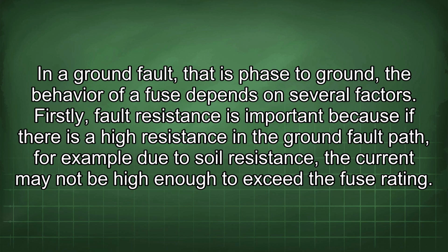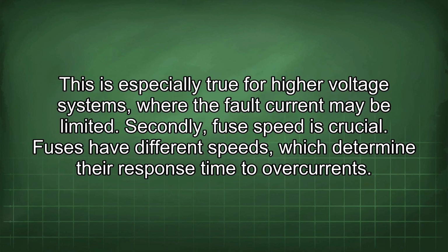Firstly, fault resistance is important because if there is a high resistance in the ground fault path, for example due to soil resistance, the current may not be high enough to exceed the fuse rating. This is especially true for higher voltage systems, where the fault current may be limited.